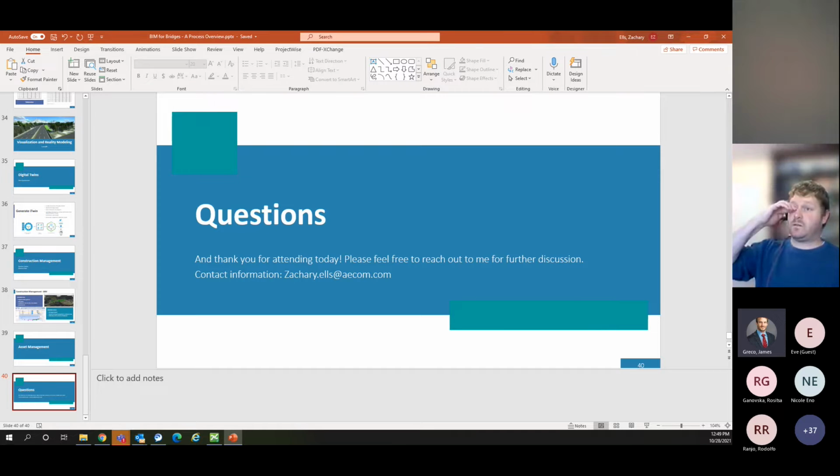So we're using ProjectWise. Bentley's associated with that since that's a Bentley product as well. So our workspace has been saved on ProjectWise and mapped that way, configured so that when you open up a specific OBM version or ORD version, it loads that specific workspace from ProjectWise. The model itself is really a DGN, and those are saved on ProjectWise as well. So anyone can go in and open that file format.